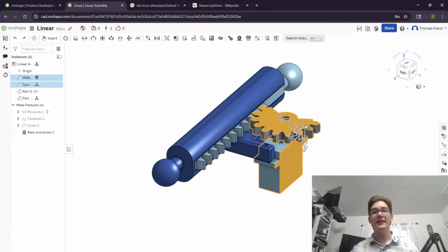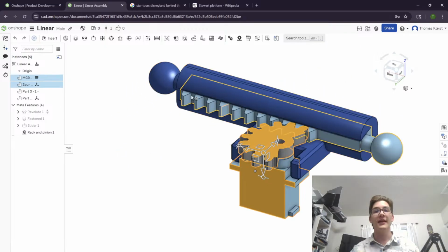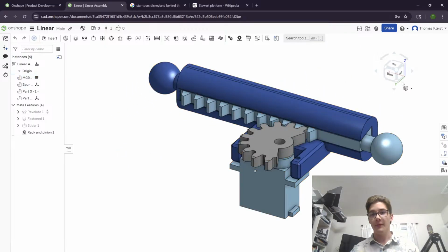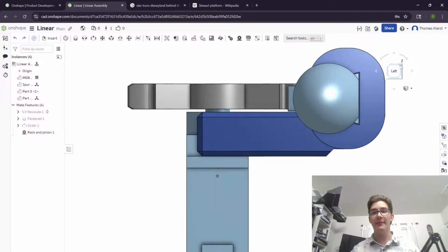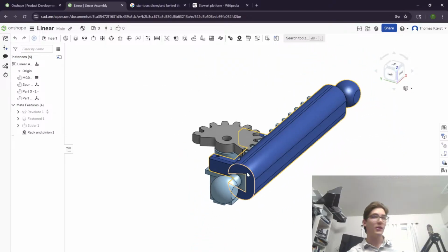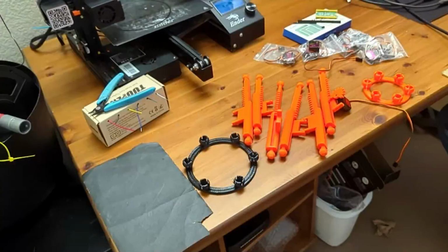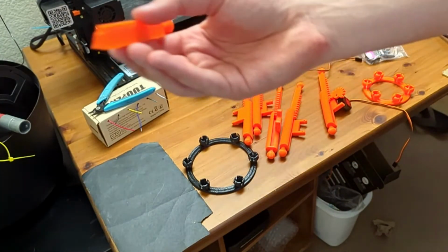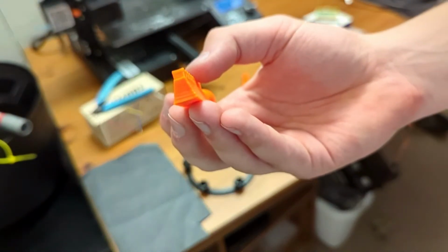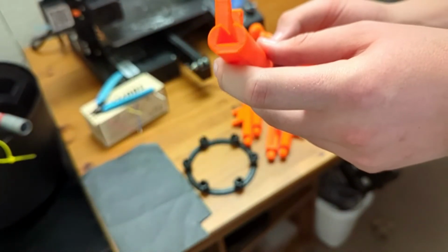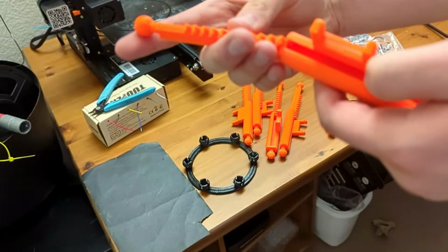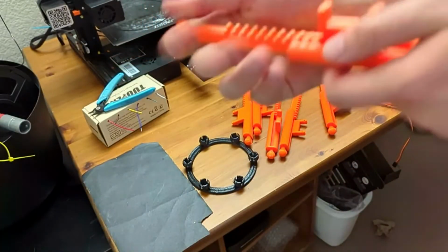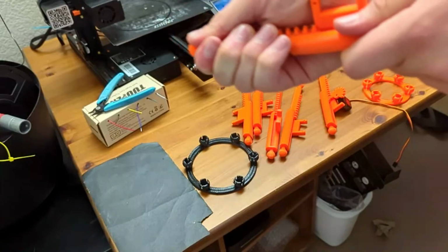And then I've got a pinion gear driving a rack, and this rack actually just sits in the carrier here with a little trapezoidal pattern so you can't pull it out from the side. And you can kind of see that here if I do this. This pattern's got the trapezoid, the holder has a trapezoidal slot, and they just fit together just like this. They slide in and slide out.